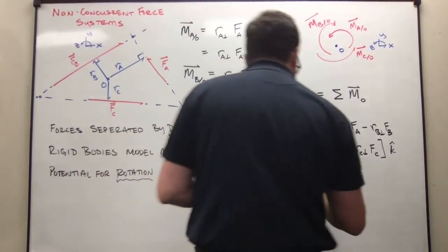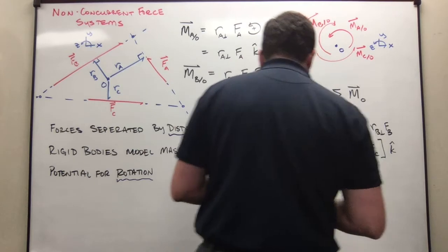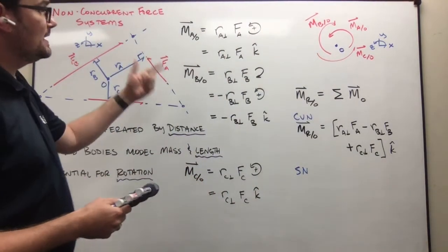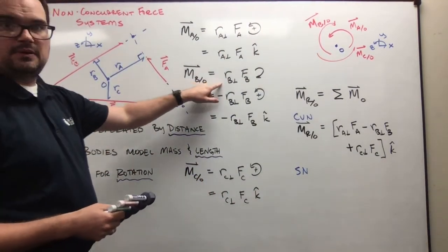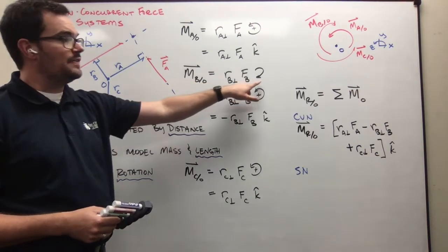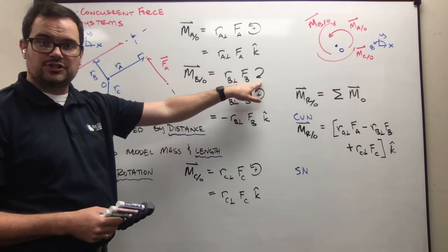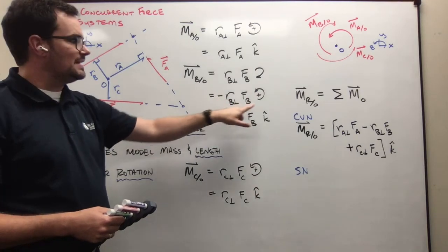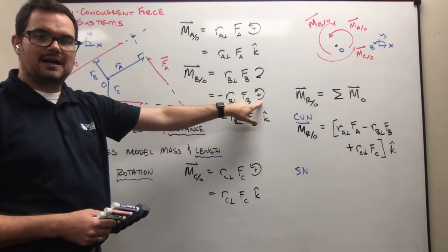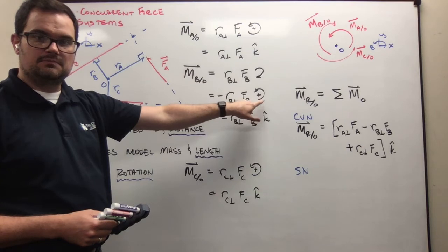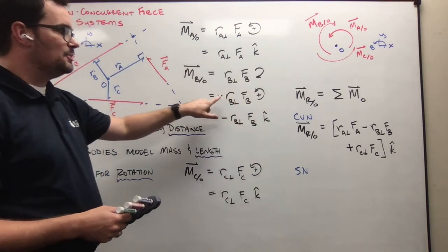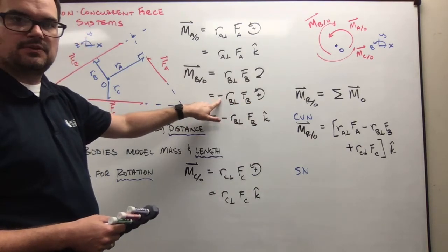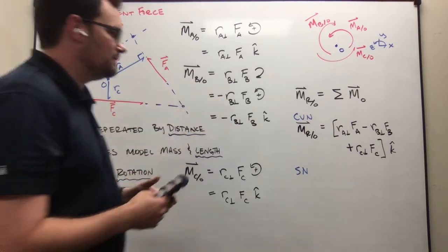In scalar notation, we can do the same thing where we could collect the terms. Now, the tricky place will be when we look at a negative moment. If we've drawn the arrow in the negative direction, we're going to have to reintroduce that negative sign. So most of the time, I'm going to encourage you to draw the positive moment sign convention, our assumption here, and then put the negative sign if it's in the opposite direction, just like we did for our resultant forces.